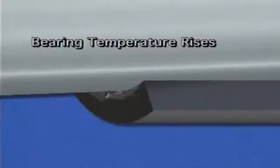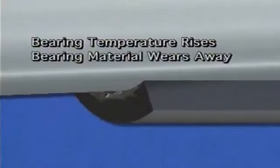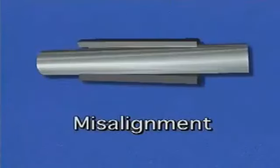The temperature of the bearing rises because of increased friction, and the bearing material wears away rapidly from the continuous contact with the shaft. The increased operating temperature can also cause other problems in the bearing that may result in failure. The lubricant in the bearing could break down, or the metal in the bearing could melt.